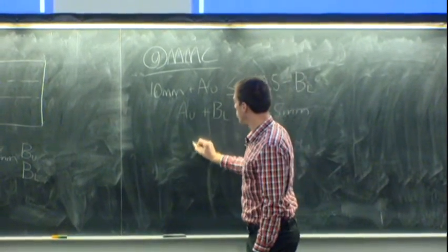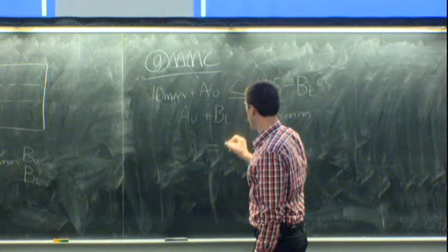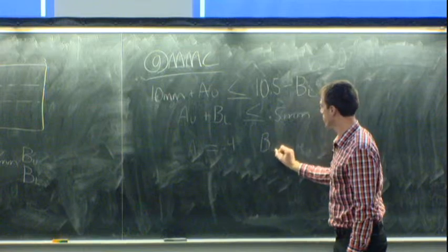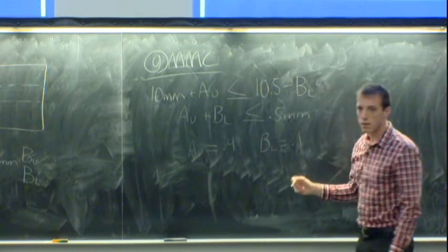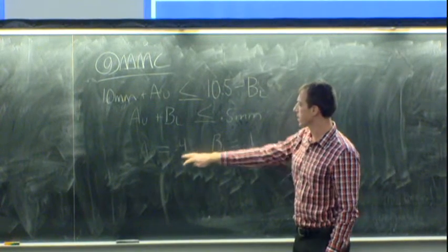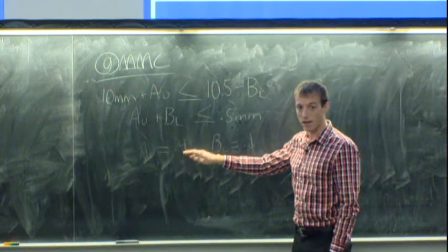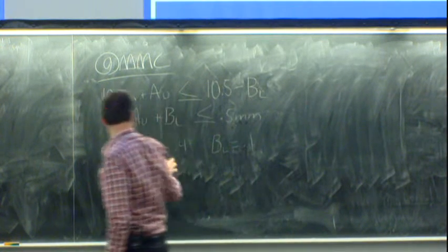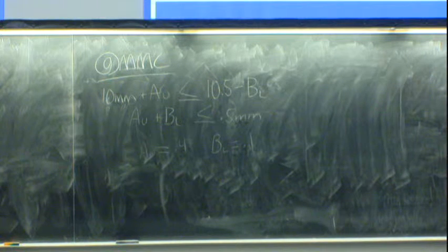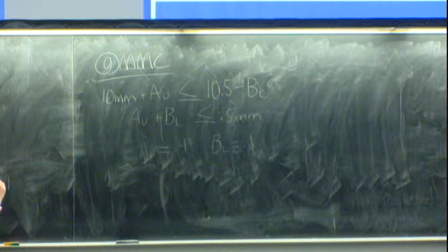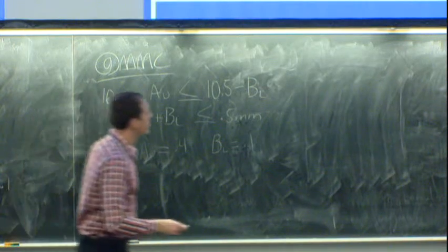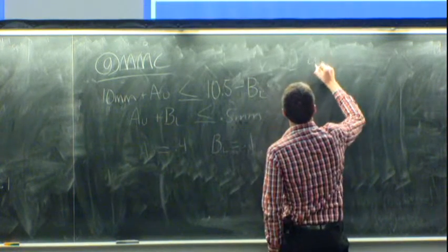So I'm going to set AU equal to 0.4. And then I know for BL, for the lower tolerance on B, I can have 0.1. Does that make sense to everybody? So I'm just taking my 0.5 and I'm choosing not to make them even. I'm picking what I want so that I can manufacture easier. So I've got 0.4 for my upper, and 0.1 down here. And you make that negative because that's a lower tolerance. Okay? So at least material condition, you do a similar operation.